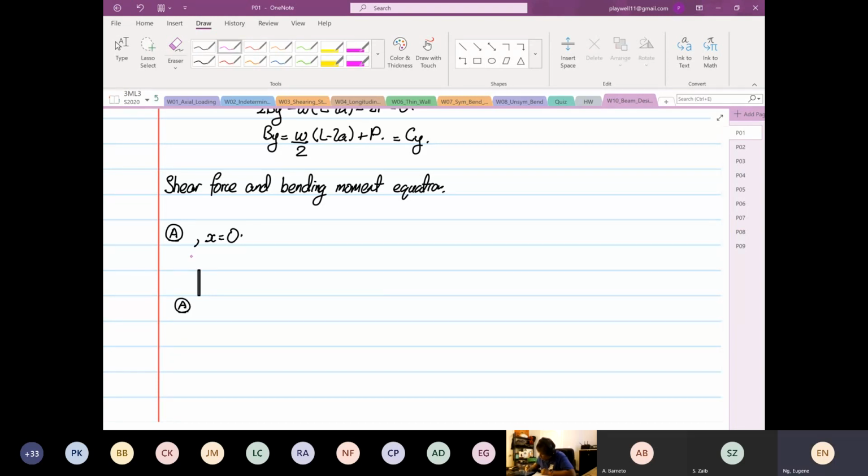So at point A, we know that we have a force coming down, which is P. This is on the left hand side, LHS. On this thin line, on the right hand side, later on you'll see this better, you're going to have a shear force V as a function of x going down, and then moment going anti-clockwise, M as a function of x. I will elaborate on this further when we do the next section. So we're going to stick with this convention first. And then our variable over here, this is our datum, this is our slider, x.